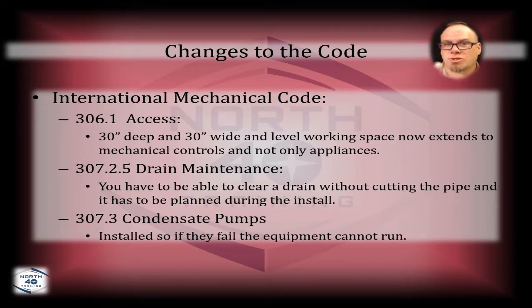Most pans come with two drains, right? You've got a primary and a secondary. You have to have it hooked up. Some places allow you just to have a short little overflow, right? The wet switch that comes out in a stub, so that if you get water into that secondary drain hole, it cuts off the appliance. Okay, whatever the case, you've got to have the secondary drain hooked up.